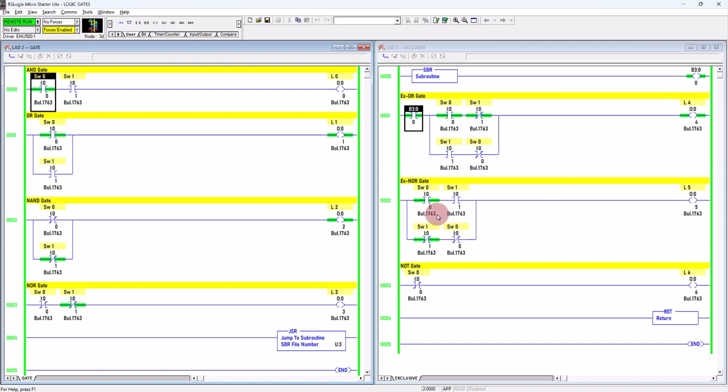Okay. Similarly for this one. 1 times 0, 0. 1 times 0, 0. 0 plus 0, 0. Nothing happened. And then because this one is 0, this one is triggered. As I mentioned, the switch 0 external physical switch is pushed to close. It will energize the internal LED 0, and then it will trigger all the relevant switches. So this switch 0 is triggered from normally closed to open. So it is 0, so the output is 0.